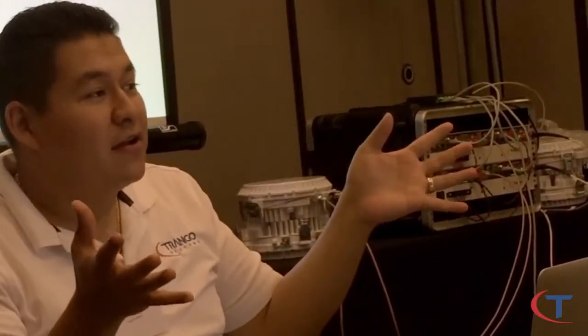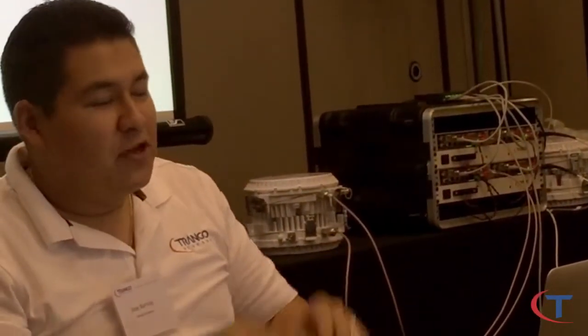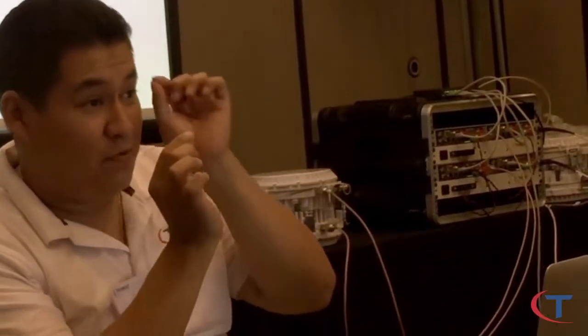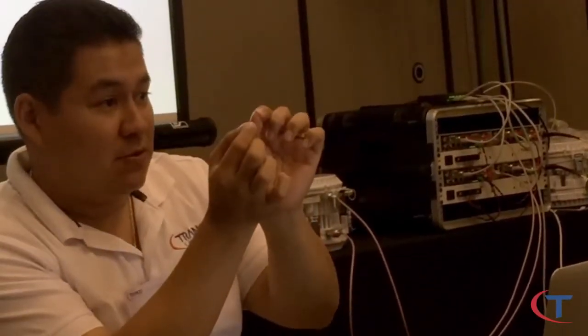Now, one way to check that is you can always grab a voltmeter and put the tip to the center conductor and then to the outer conductor. It should be negative 48. But I always tell customers, be very careful, because if you just touch them together, again, you blow the fuse inside. So with audio power on, it should give you a negative 48 when you put the center tip and the outer tip in the voltage. But don't touch those tips. If not, it's coming back.